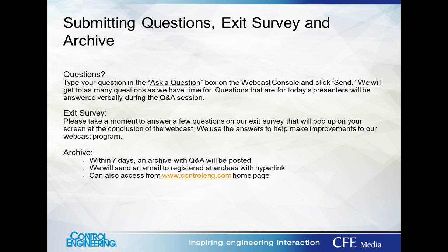And then the question, how do we do that without an optimizer, is where do those optimization targets come from? They can come from the business level, from the site-wide production planning. They can come, and usually do come, the great majority of them, from engineers who configure targets and limits based on process design knowledge, from operators who might take the plan passed down from production planning on a daily basis and change things based on feed rates and product grades, etc. On occasion, there needs to be a live calculation for a target, but that's quite the exception.